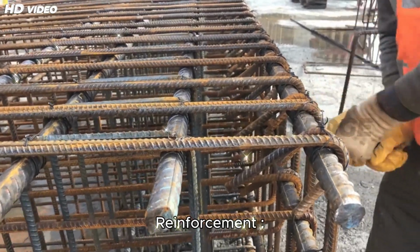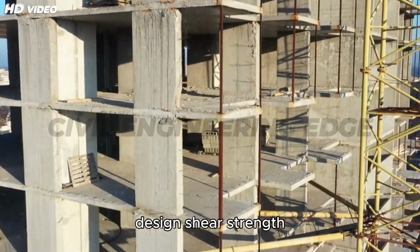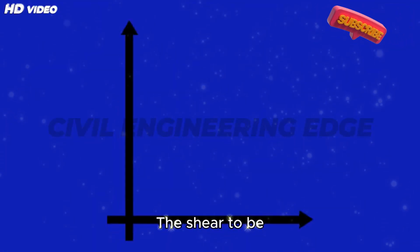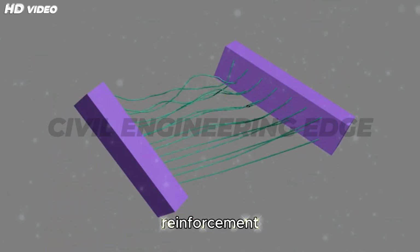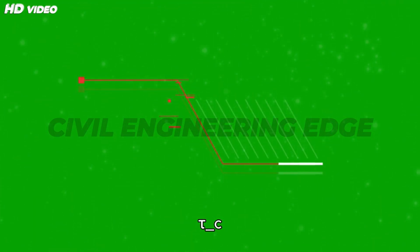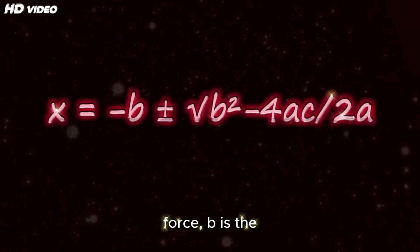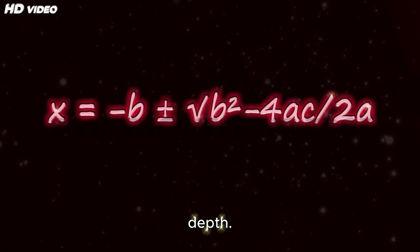Design of shear reinforcement. When nominal shear stress tau v exceeds the design shear strength of concrete tau c, shear reinforcement must be designed to resist the excess force. The shear to be resisted by reinforcement is thus Vus equals V minus tau c b d, where V is the factored shear force, b is the beam width, and d is the effective depth.